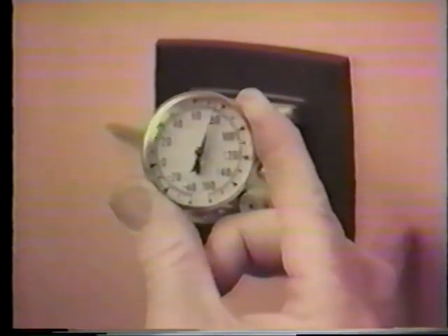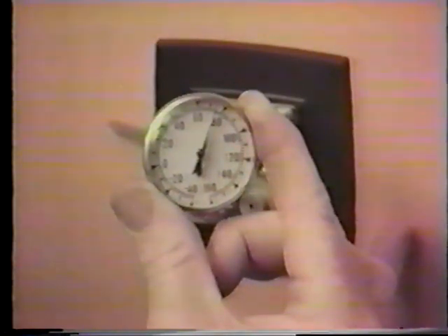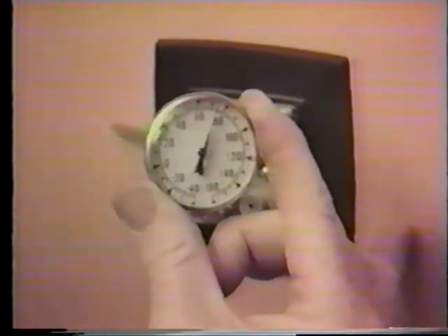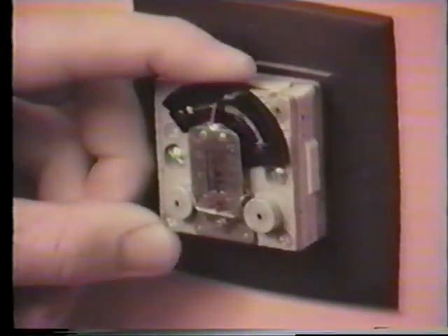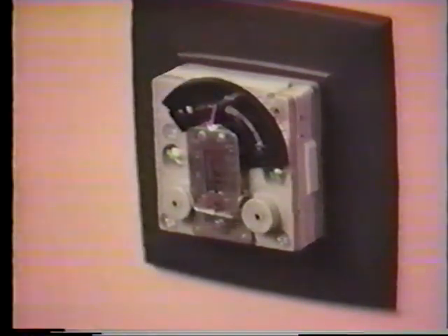Now, measure the ambient temperature in the space the thermostat is controlling. This temperature must be measured at the thermostat to accurately indicate the temperature being sensed by the bimetal element. Set the thermostat set point to match the ambient temperature measured in the previous step. This is the reference point the thermostat will be calibrated to.